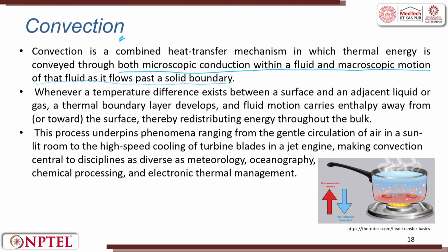Whenever a temperature difference exists between a surface and an adjacent fluid, for example air or gas, a thermal boundary layer develops, and the fluid motion carries enthalpy away from or towards the surface, thereby redistributing the energy throughout the bulk. This process underpins phenomena ranging from the gentle circulation of air in a sunlit room to the high-speed cooling of a turbine blade in a jet engine.